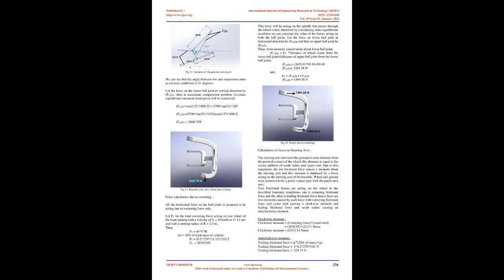Steering knuckle. The steering knuckle is a very vital component that integrates the wheel assembly, that includes the steering, suspension, and brakes, and is connected to the frame with the help of suspension arms. It also plays a very important role in the steering mechanism by using the linear motion of the tie rod to give a turning effect to the wheel assembly, following Ackermann geometry.